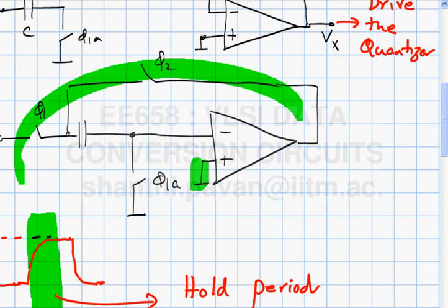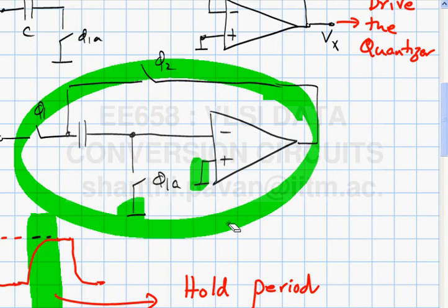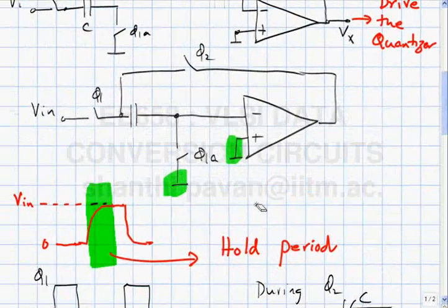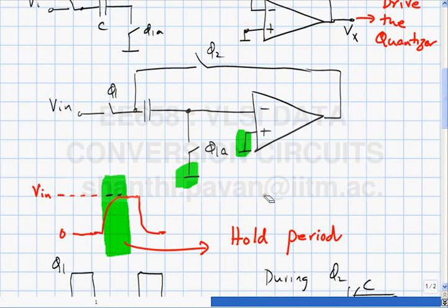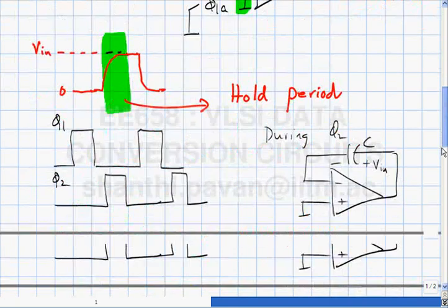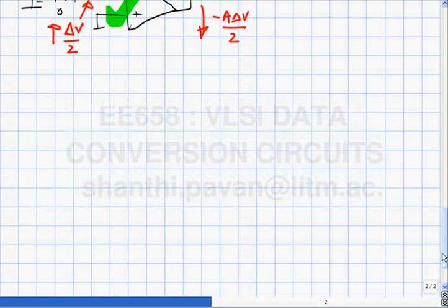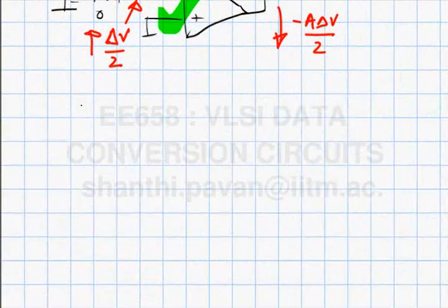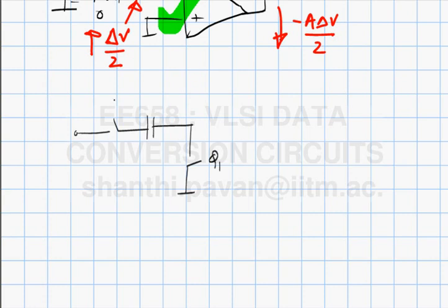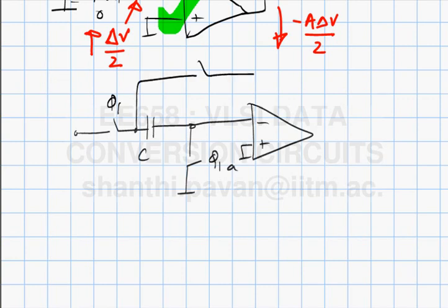As I have indicated several times before, whenever I say ground in a single-ended op amp circuit, what does that actually mean? What does this ground actually mean? It means VDD by 2. Now we have learnt about differential operation and all the marvelous advantages that accrue with it. So, let us look at this. This is the single-ended version we just saw.